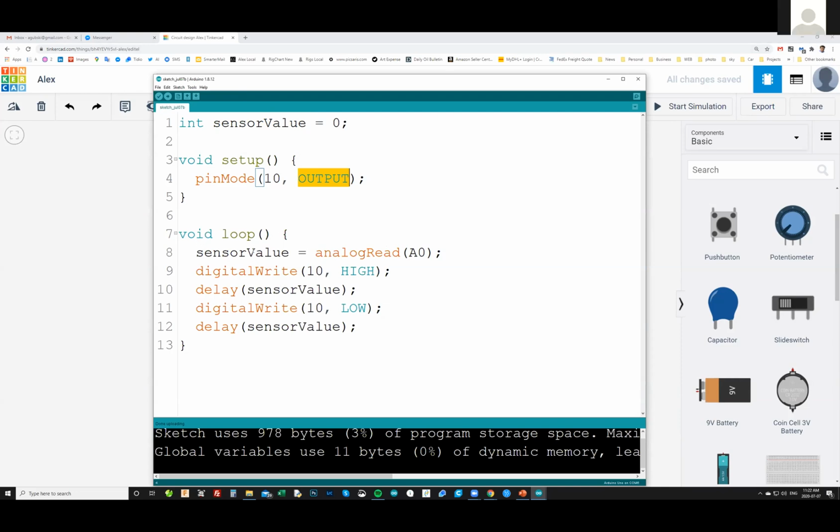First thing we do in our main loop is we read the pin A0 on Arduino, and whatever we read from it, we toss it into the box that has sensor value written on it. And then we just address this box from our delay function. So every time we ask for delay, we're saying we want to delay it not for a second or half a second, we're going to delay it for some value, unknown yet, that we will read from our potentiometer.